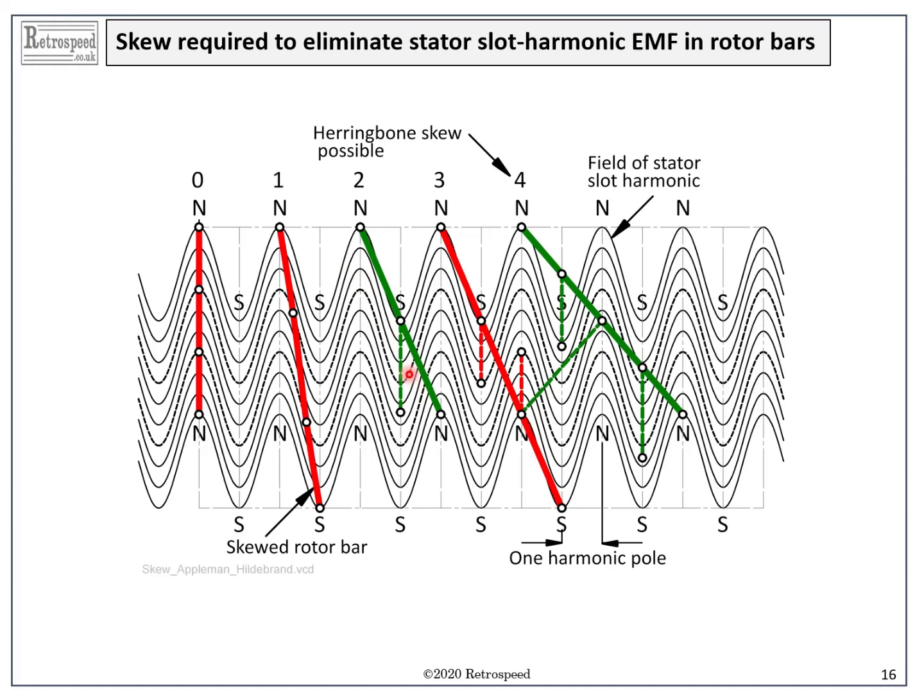A skew of only 1 harmonic pole pitch is the worst possible, because the EMF and torque in the 2 halves are additive. There might only be a small difference between 1 harmonic pole pitch and 2 harmonic pole pitches, indicating that the amount of skew is quite critical. And for some reasons, 4 harmonic pole pitches is suggested as being the best one.